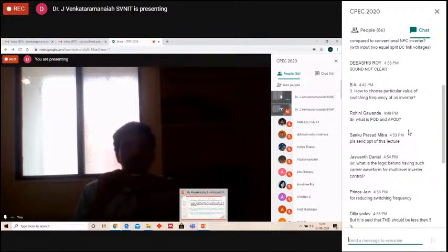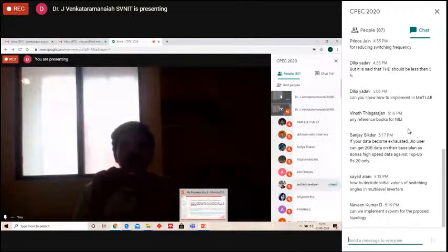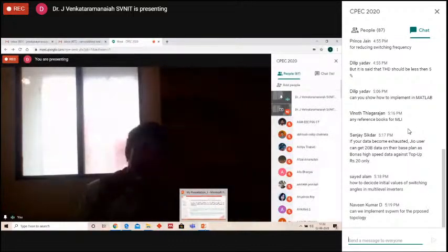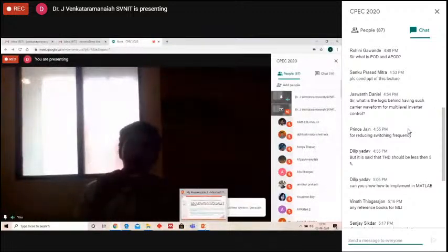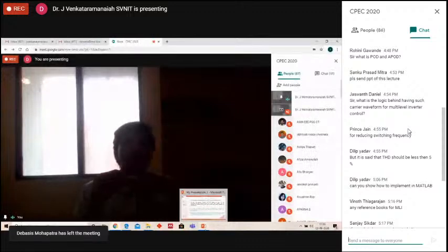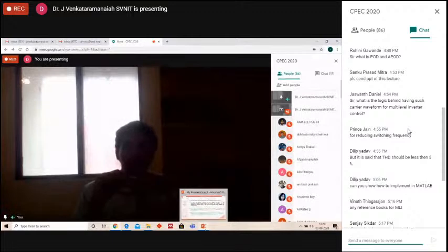Last question from the audience, Saeed Alam has written, how to decide initial values of switching angles in multi-level inverters? The initial angle problem is only difficult in the selective harmonic elimination technique, where we want to specifically eliminate one harmonic. That's why we need an initial guess. So it is a little bit tough. Otherwise, if you are not worrying about the lower order harmonics, you can choose different angles, but it is not a good way, because lower harmonics always need to be low values or nullified.